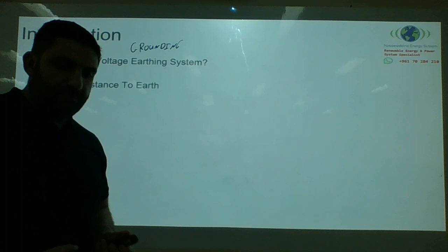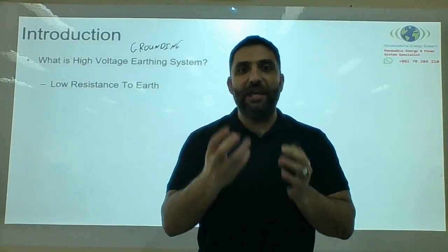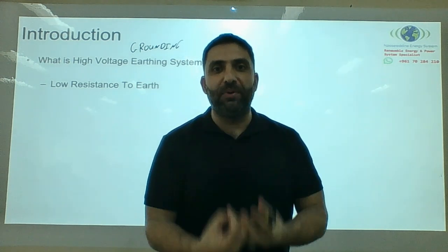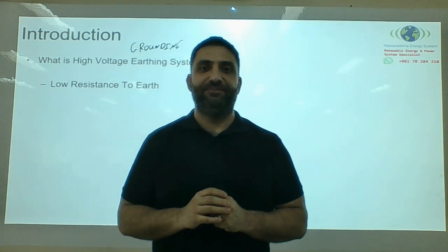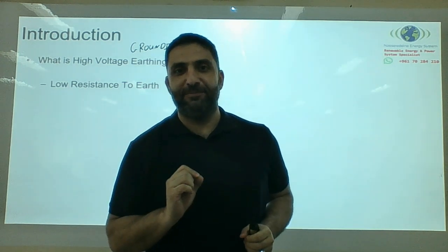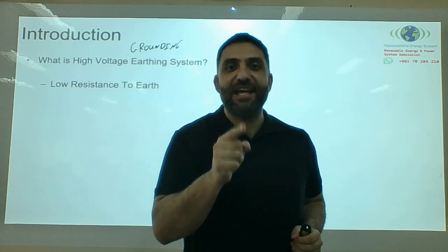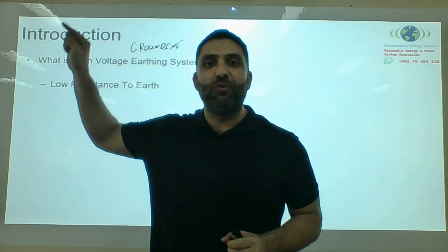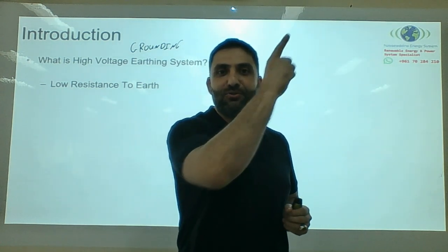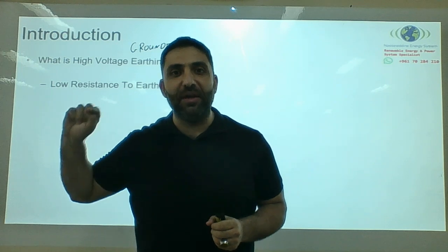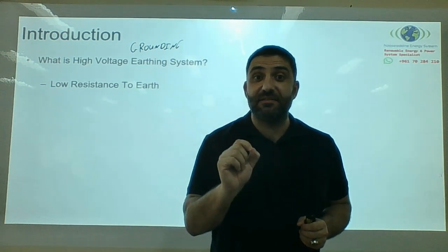What is it? Its main role is to establish a low resistance path to absorb the fault energy and return it back to the source. Remember what I'm going to say now. The fault current always has to return to the start, where it's generated. Always has to return back to the start where it is generated. Remember this. Never forget this.